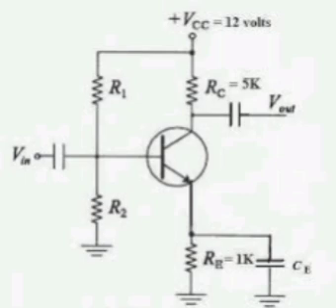Ruggedness: these transducers can usually tolerate a high degree of shock and vibration, especially when the core is spring loaded, without any adverse effect. LVDTs are simple in construction, stable and easy to align. Low hysteresis: LVDT shows low hysteresis. Repeatability is excellent under all conditions.